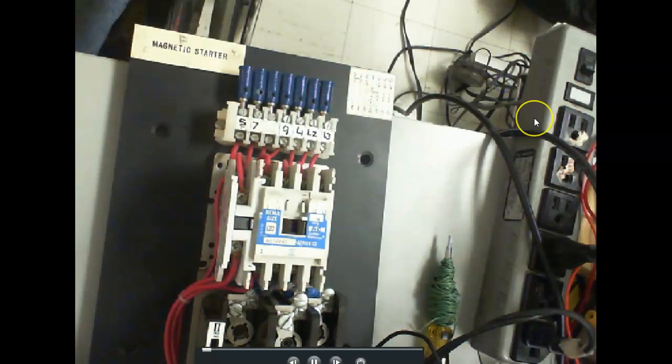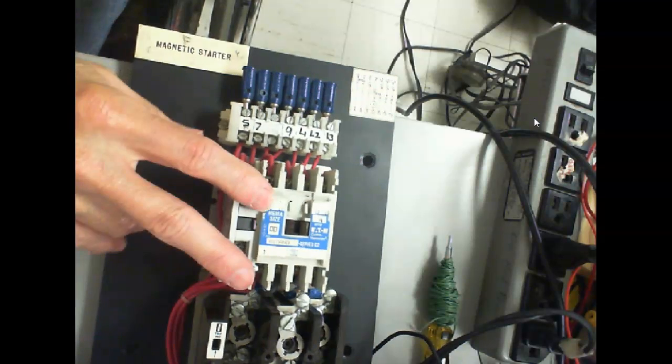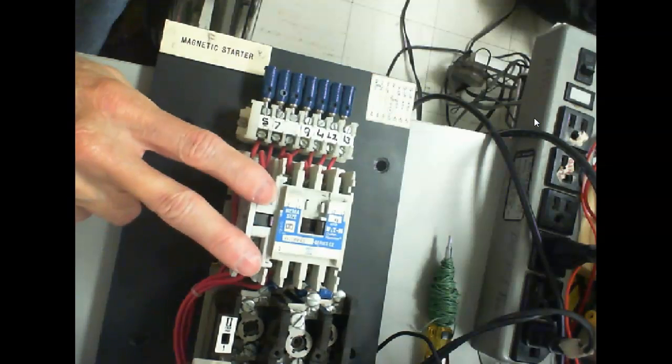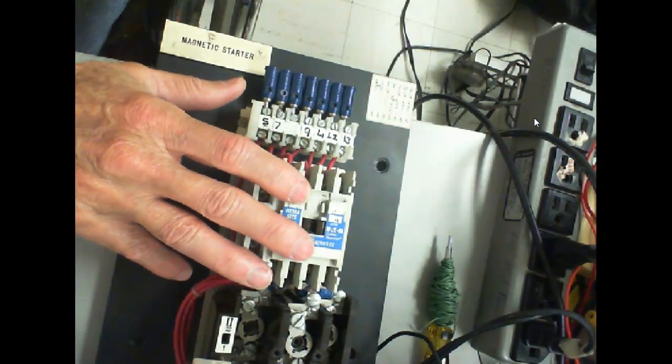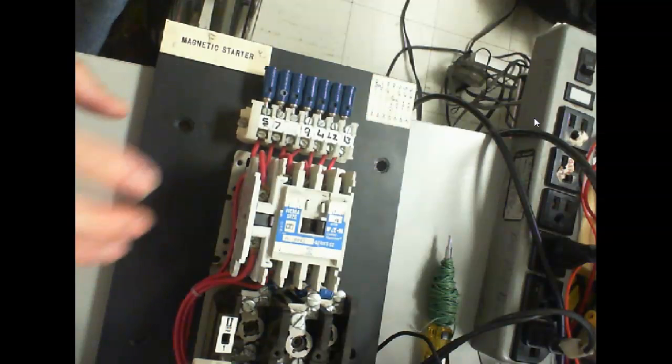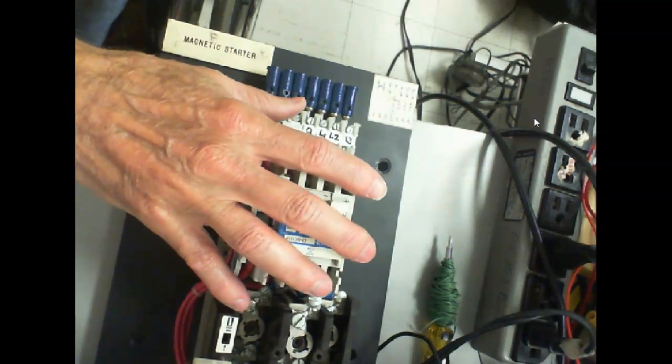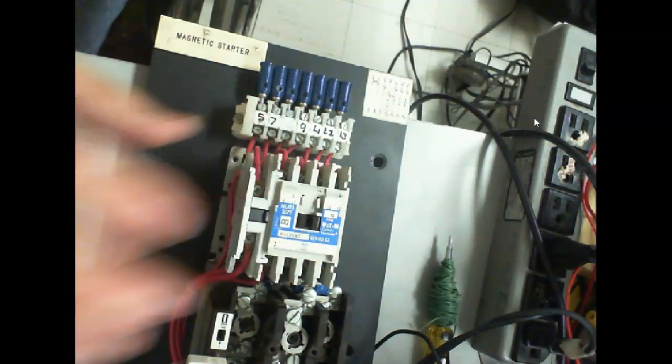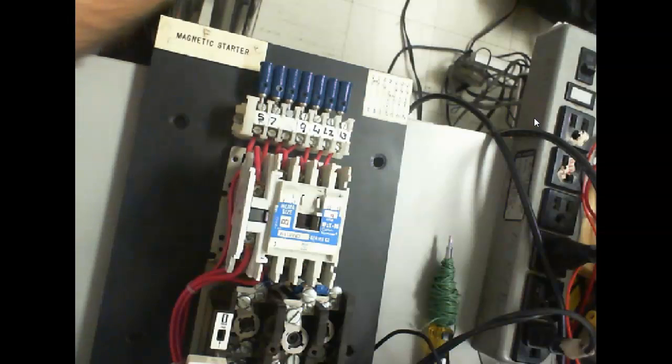So like I said, it's up to you which one you want to use. If you want to use the one with the electronic overload on it, that's fine, but you'll have to get the manual. They're usually in the blue tables inside the drawers right there. That shows you how they're wired, or you can use these. Most of the time we're going to start out using one, but when we get to the reversing circuit, we're not going to use a true reverser. We'll just use 2 of these to reverse it. And there's more back there on the shelf if you need them.